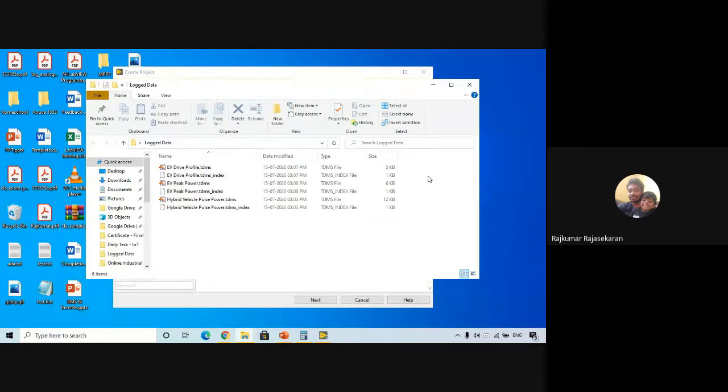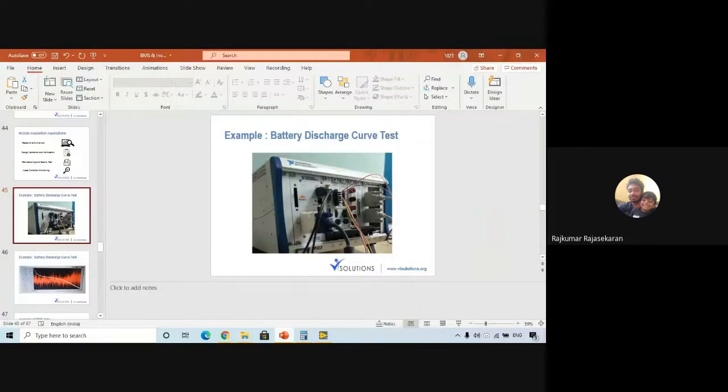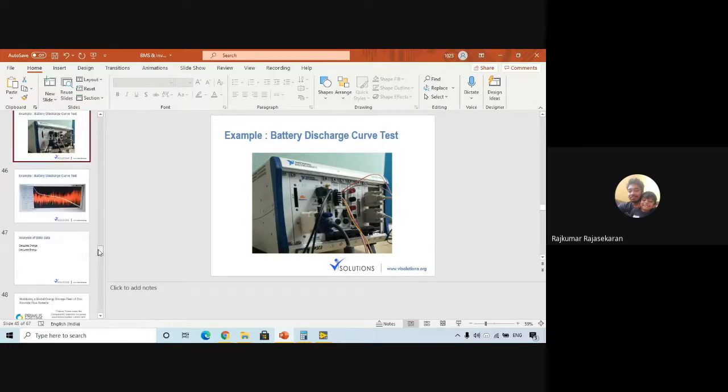After calculating this, if you want to find the state of charge and state of health by an available technique, you can proceed to do it. There are ample opportunities you can execute using LabVIEW. You can do a fixed calculation, where you already know the capacity of the battery and divide by that value, or based on certain parameters you can calculate the state of charge. That will be equation development, which will be done by you. So we have just told you that this is the path you can go.